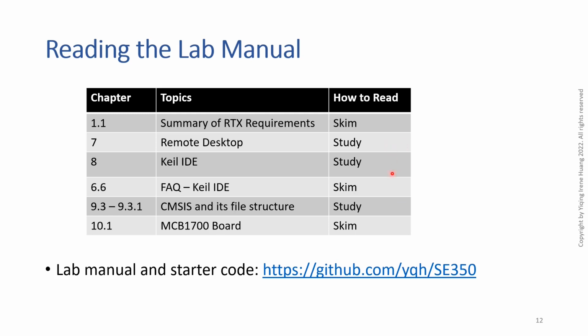You have to follow the steps, and how to create your first HelloWorld application so that you familiarize yourself with the Keil IDE functionalities: the debugger, the editor, the compiler, all these things. And finally, what exactly CMSIS is and its file structure, because we use this software stack from Keil, or from ARM, as part of our lab project.